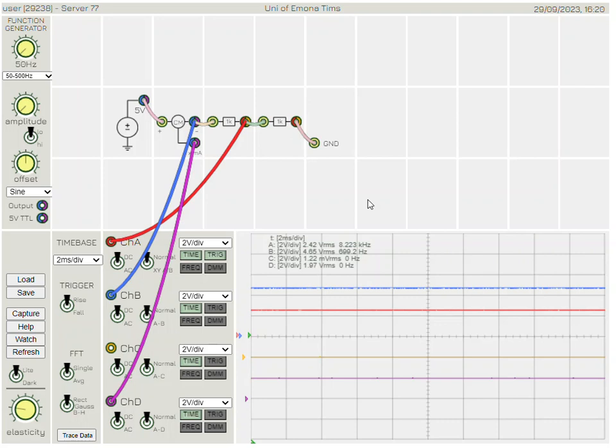And our measurements show that it's 1,127 ohms. That's very close to the expected values. Any differences will be attributed to the fact that this connection may vary, and it is not always exactly 110 to 120, plus or minus a few percent. And these components also have a tolerance of a few percent as well. So that's the end of that simple example on how to measure the resistance using voltage and current measurements.